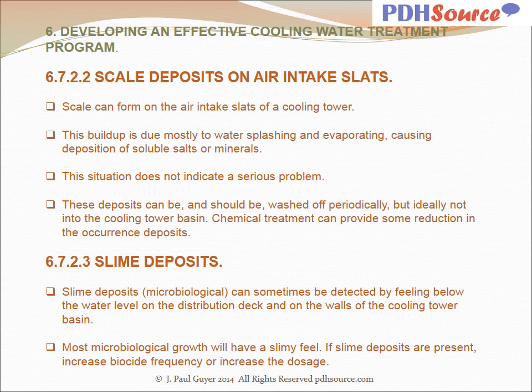Slime deposits can sometimes be detected by feeling below the water level on the distribution deck and on the walls of the cooling tower basin. Most microbiological growth will have a slimy feel. If slime deposits are present, increase biocide frequency or increase the dosage.